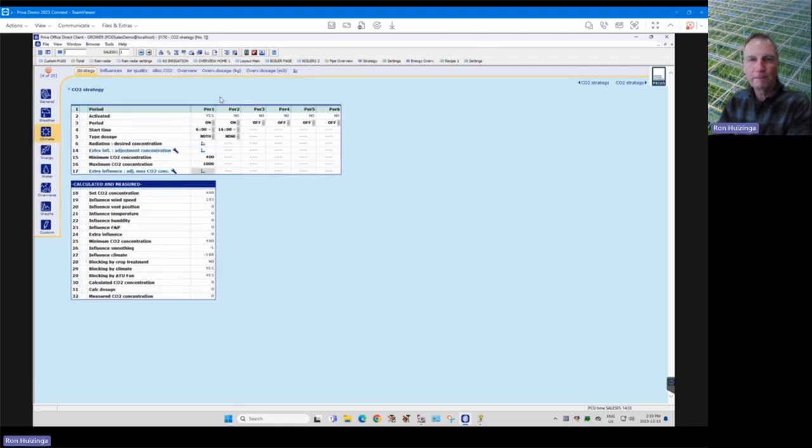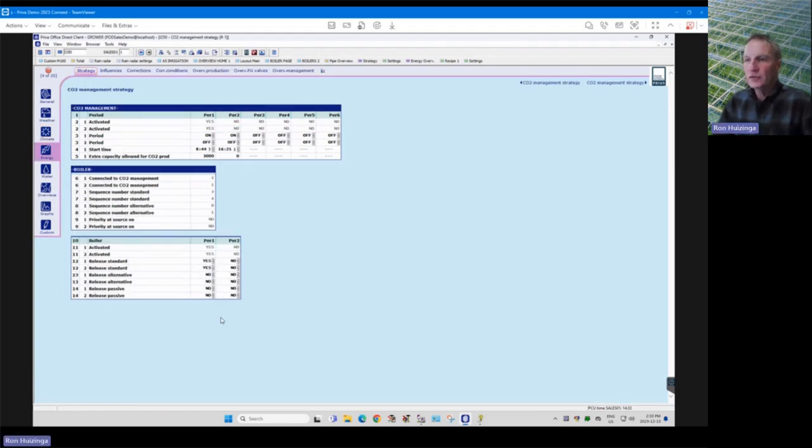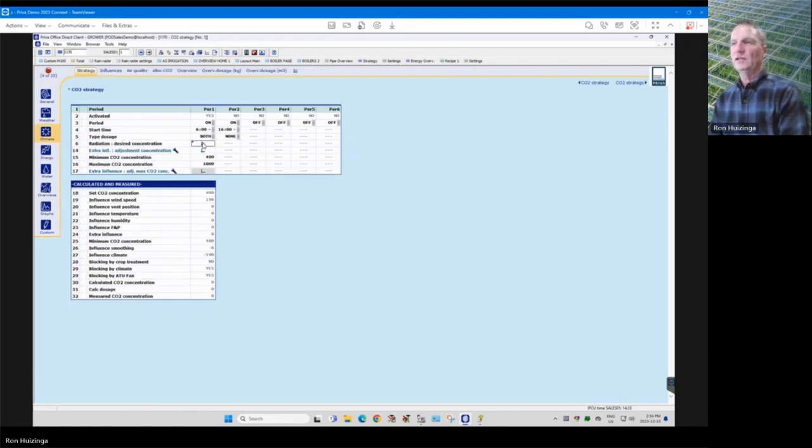But if you have this set to no, the lights, I'm sorry, the CO2 boiler and the fan are not going to run, because passive is not on. So you should set this to yes. It's easier to leave this on yes all the time. Then whatever you set in here, if you do decide to change your mind, it will run for passive.